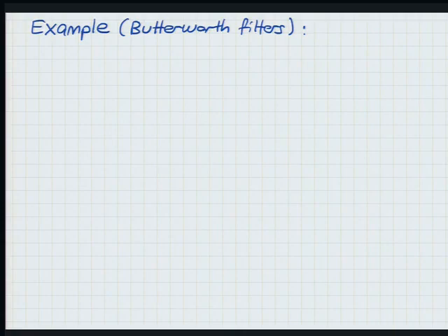Remember that block diagram, you first do C to D, and then do your digital processing, and then you do D to C, right? Even though you could be implementing a digital filter, well, first of all, you have to make sure before sampling that you're not going to have aliasing, right? Before sampling, you have to make sure to cut off the high frequencies of the signal, or at least reduce them to a negligible level.